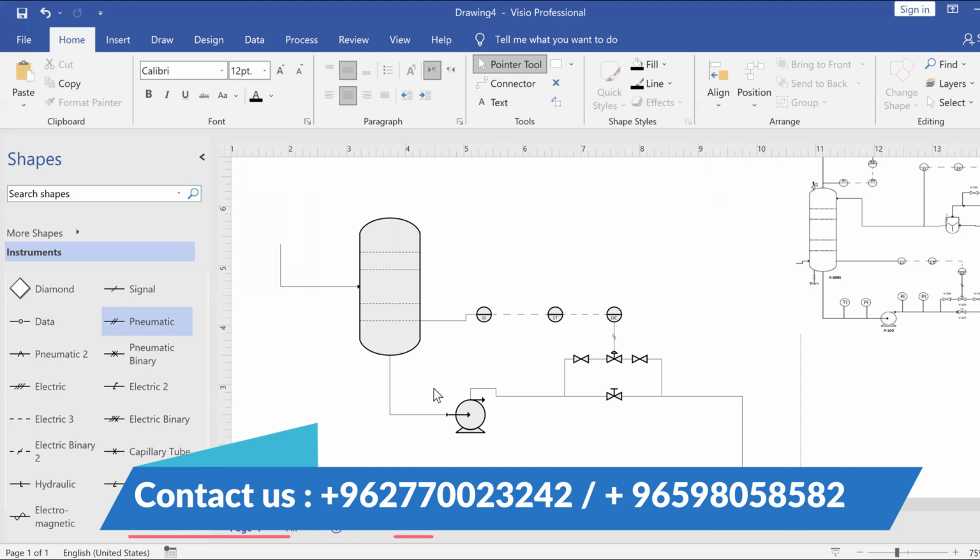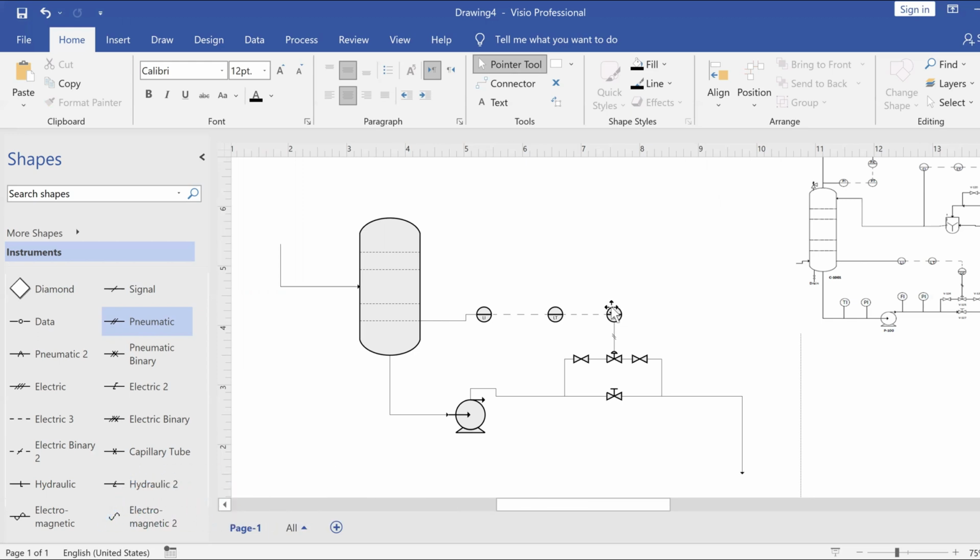So as we said, we have a level indicator, transmitter, and a level indicator controller. If the level in here is too high, the level indicator will indicate that the level is too high, and it will send its signal all the way to the controller. The controller will order this valve to increase its opening and allow more liquid to flow out, so increasing the flow rate of the liquid leaving, and therefore decreasing the level, and vice versa. If the level is too low, it will just order it to decrease its opening, so the level inside the absorber will increase.